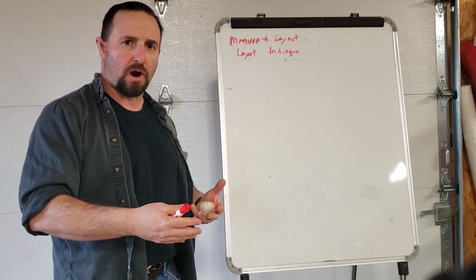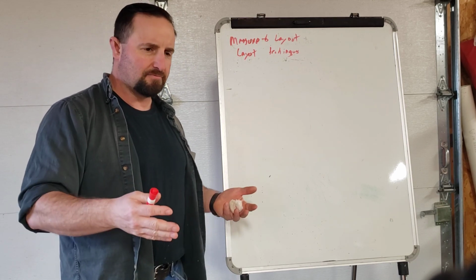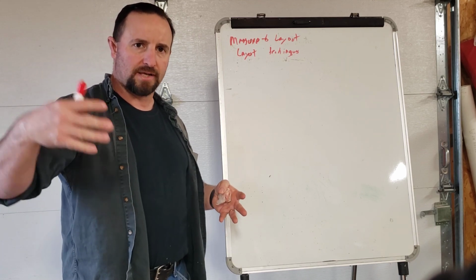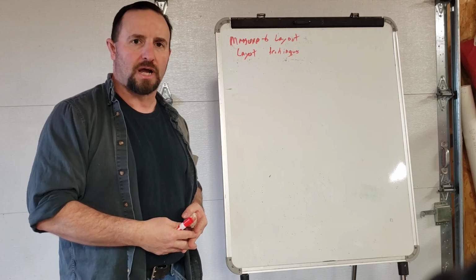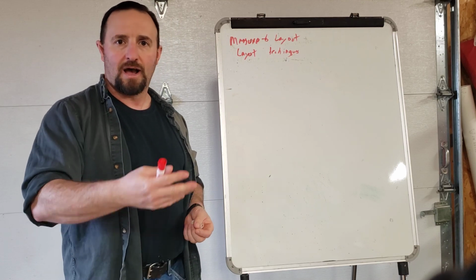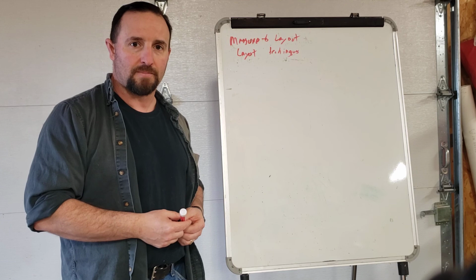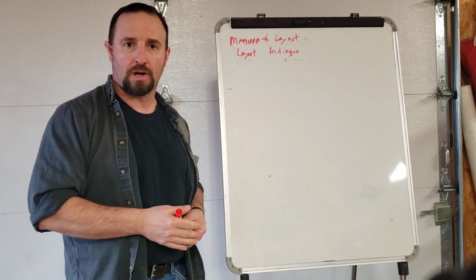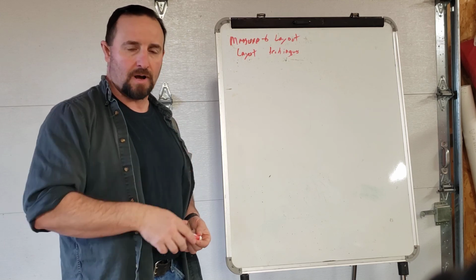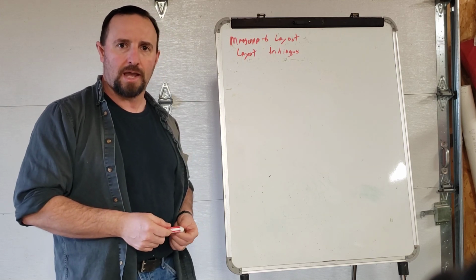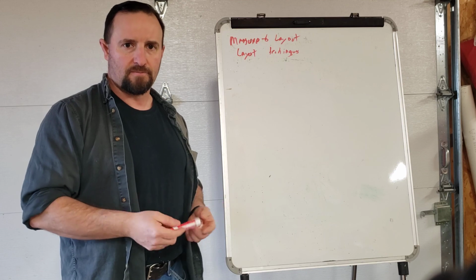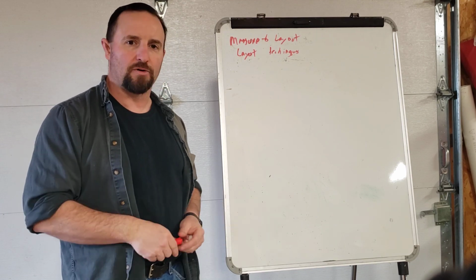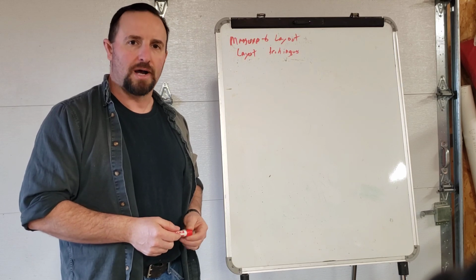And when we're doing small parts like what you're going to do for Oxy, they're not going to be too far off. When you start dealing with bigger and bigger things like buildings, you'd be surprised how much tolerance is allowed. I personally have run into issues where we started measuring off of a door as it came through, a concrete cutout, for one set of measurements, and then a building pillar for the other set. Well, on the print, everything worked out perfect. The real world, not so much.